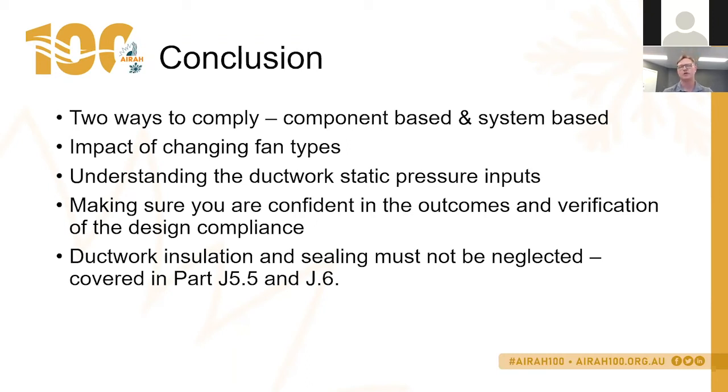So if you've got an 83% efficient motor and you've got the absorbed power by the fan from the fan manufacturer that they need to drive the fan to a certain speed, then you need to take into account the motor losses. Quite a lot of the manufacturers provide the actual motor input power, so they have already taken into account the selected motor and the losses for that particular motor.